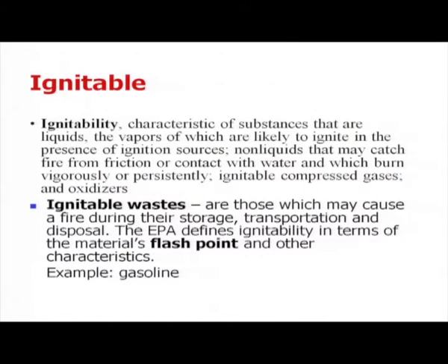The third property is the ignitable property of a particular hazardous waste. What is this? The characteristic of substances that are liquid, the vapors of which are likely to ignite in the presence of ignition sources, and non-liquids that may catch fire from friction or contact with water, and which burn vigorously or persistently, that is, ignitable compressed gases and oxidizers. Such a property is called ignitable waste.